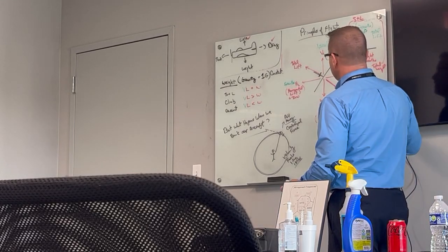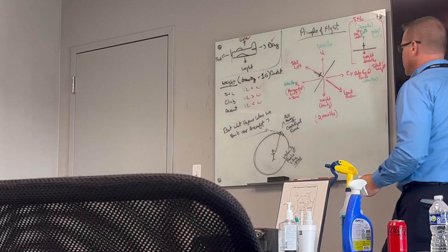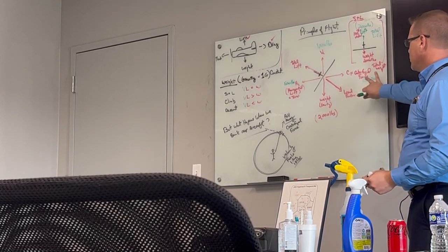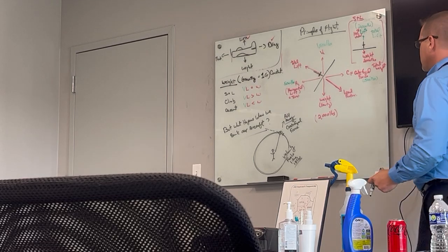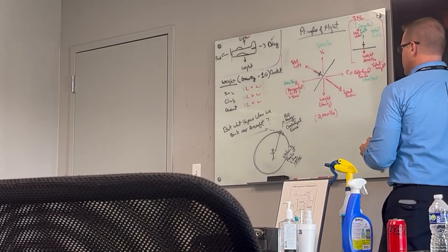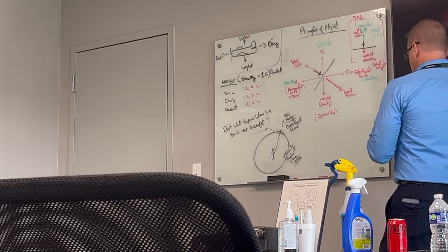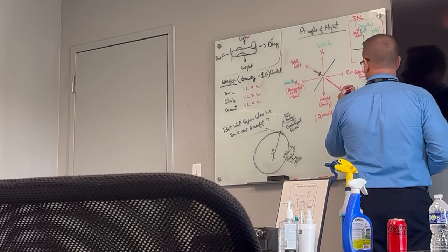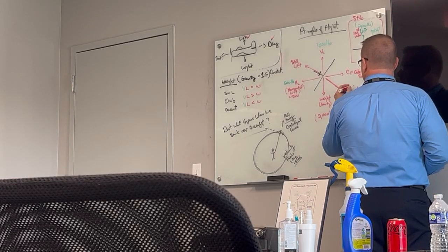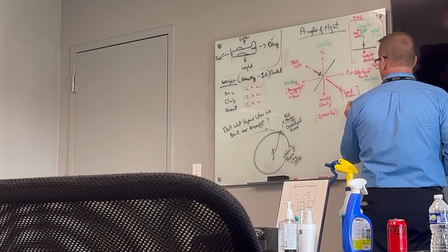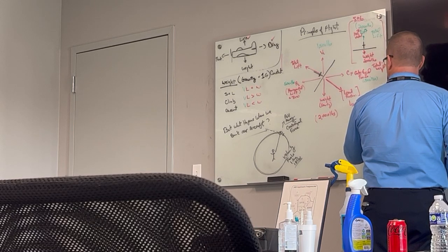Same thing with the plane. The plane's being pulled to the inside of a turn. It doesn't want to do that. It wants to keep going straight. So the force that's opposing that turn and that's causing this to feel heavier is centrifugal force. So we have a new term, which is load factor. And what is load factor? Well, load factor is nothing more than weight plus centrifugal force.